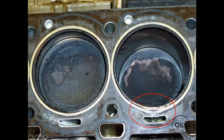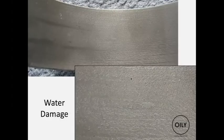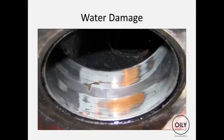You can see the carbon deposits there, and here they're getting washed off by the water while the engine is running. And that's just because of using the wrong antifreeze in that engine. Head gaskets cause all sorts of problems: engine overheating, loss of ring tension, bearing failures. This is bearings from that engine with the water damage on the bearings. Water damage on a big mining engine.